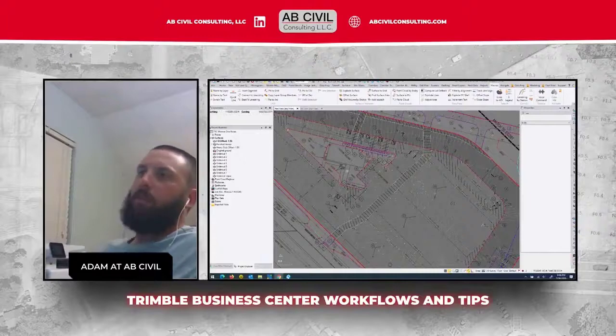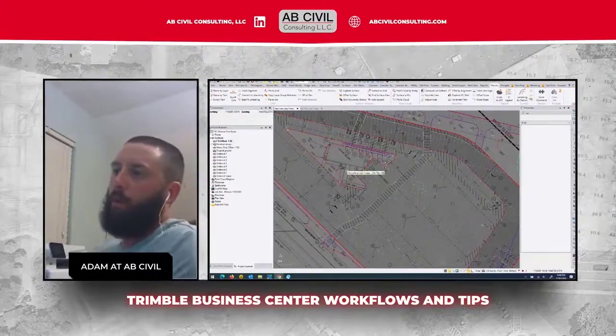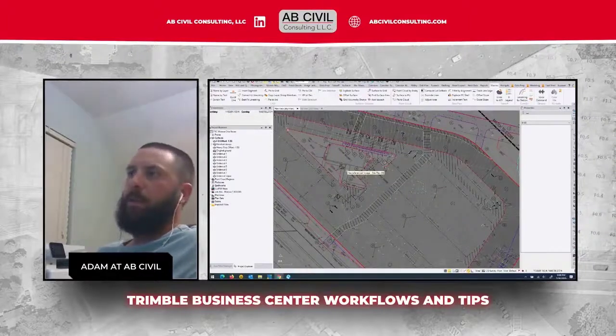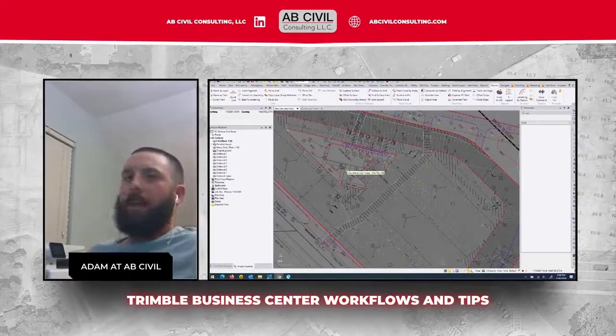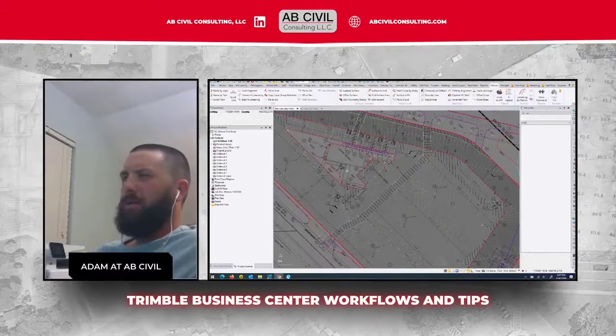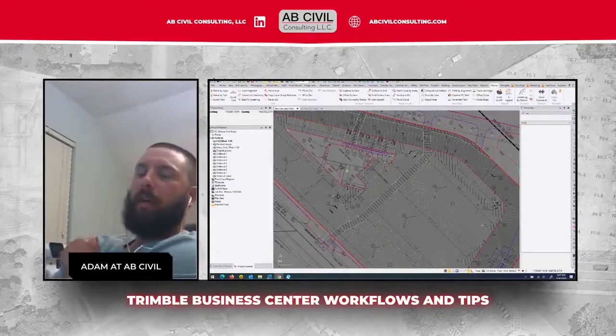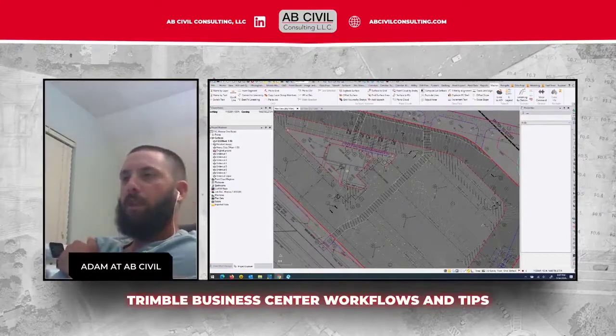The contractor got everything cut down to subgrade. The owner's representative, an inspector, went in, took a look and said, maybe there's buried topsoil or something, no, we need you to cut this out. At that time, normally what happens is you cut it out, and they will take a measurement to document how much material you took out. A lot of contracts have a line item. Even a lump sum contract will have a line item for undercut. Often it's cut and replace.